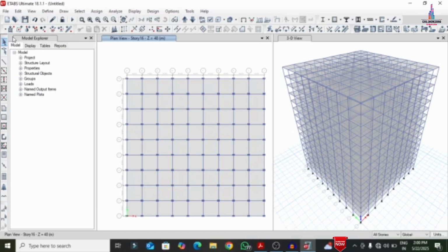Now after this we have to delete all the sections which are not necessary for this building model in order to make the structure a tube-in-tube structure. So here, to make the building structural model into a tube-in-tube structure, I need to delete these particular frame sections and slab sections present for this building. I am selecting all these members at this particular location. Go to edit option, click on delete option so that it will delete all the properties at that location. Now we can see it was deleted like this.